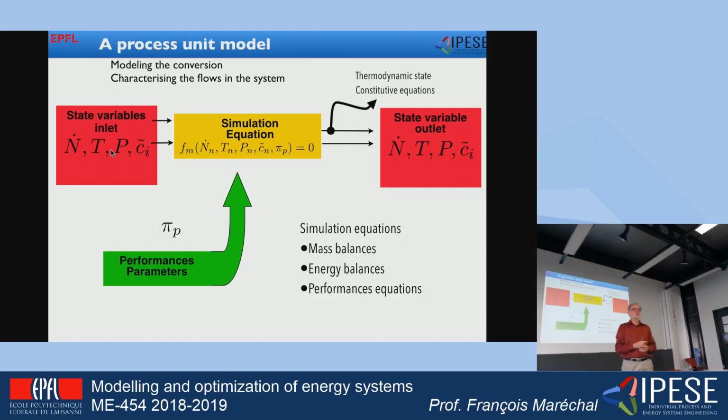So you will look in a table, in fact in a graph, not in a table directly. There are also tables that summarize the graphs, but a priori you will look at the saturation curve to see where you are. So it means that you know how to do it. If I give you the temperature, the pressure, and the fact that it is water, you will go into a book, find the table or on the internet in engineering toolbox, find the nice graphs that show the enthalpy as a function of the temperature and the pressure, and you will get the value.